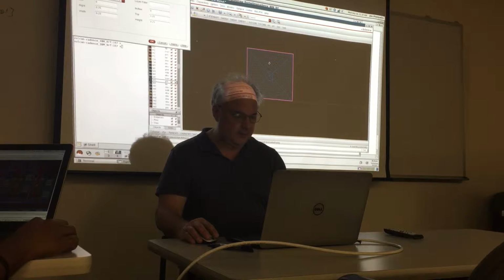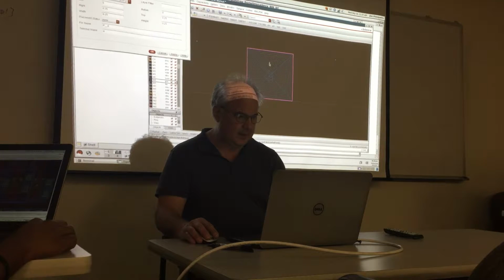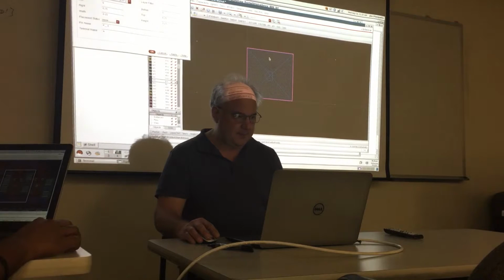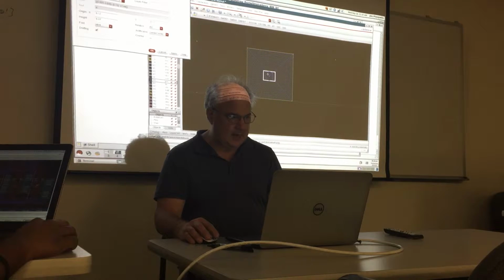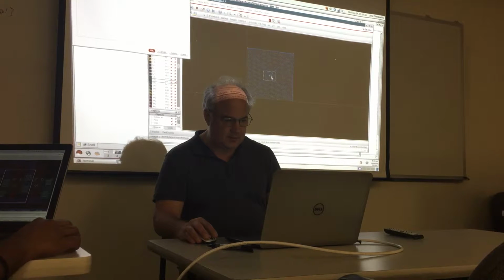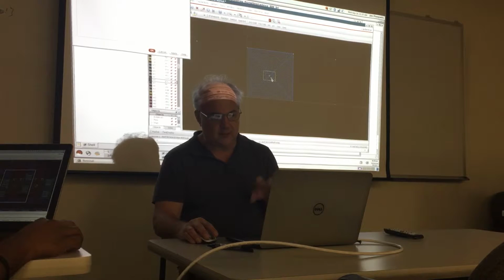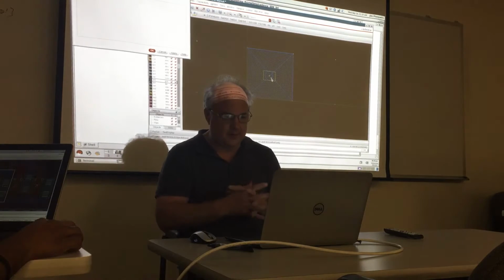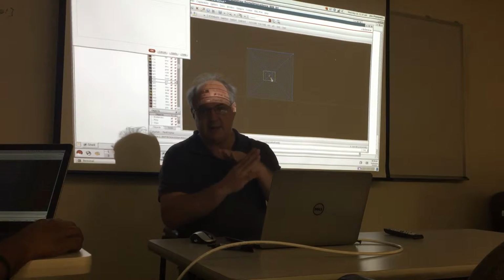You can select different items just by continuing to click, and then keep this Q properties menu up. When you get to the pin, you'll see it. As soon as you move over, you'll see that it puts a smaller or bigger rectangle, depending on how big the font is, and then it highlights that X in the middle.